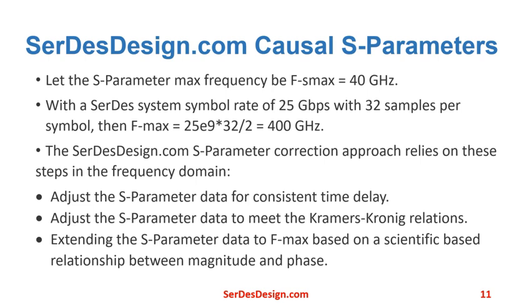SerDesDesign.com provides causal S-parameters. These have been in use for over 10 years for SerDes channels using S-parameter data. The SerDesDesign.com approach relies on correcting the S-parameter data in the frequency domain and on extrapolating the S-parameter data beyond the maximum S-parameter frequency, call that Fs-max, to half the sampling rate frequency, call that Fmax.